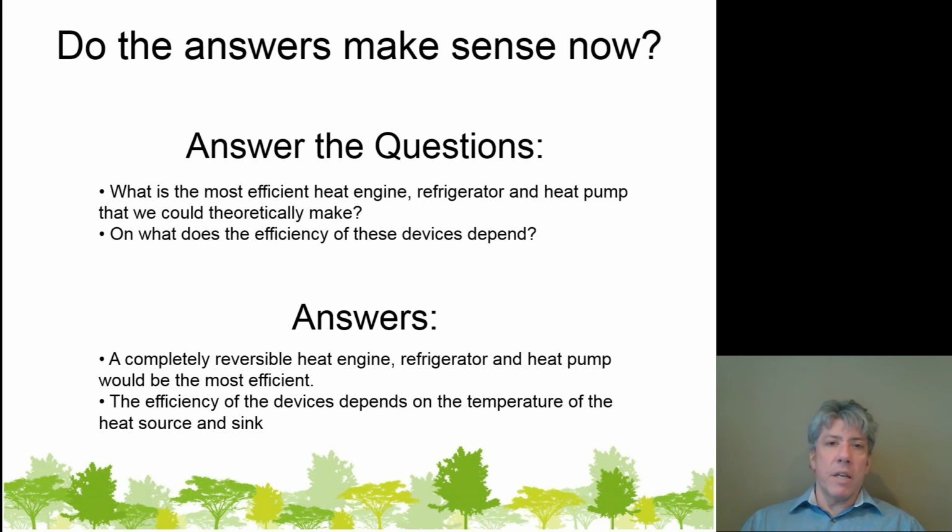But do we have any control over the temperature of the thermal energy source? Well, what is it in your car? Well, when you put the gasoline in the combustion chamber with air and you burn it, at that instant you have high temperature, hot, high pressure gases, right? Those gases are going to expand doing work. The higher the temperature of those gases can be, the higher the theoretical efficiency of the engine, the higher efficiency the engine could reach if we design it well and reduce irreversibilities.